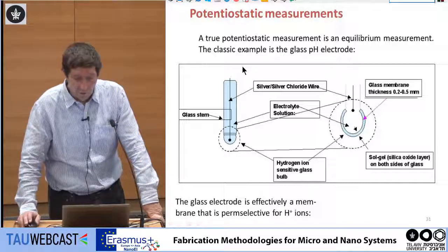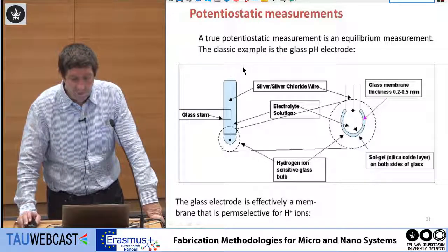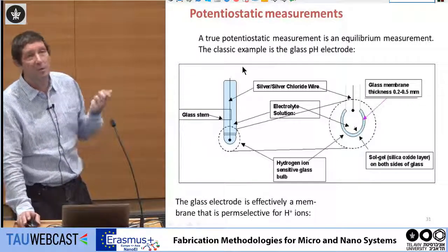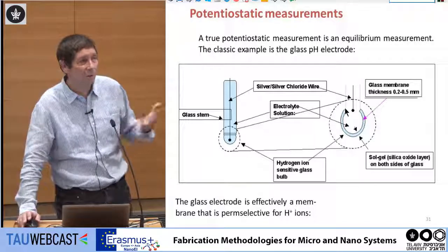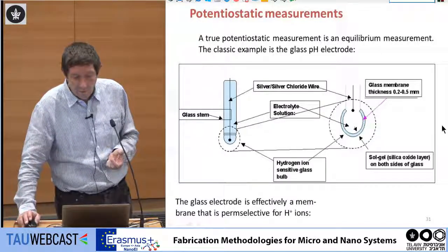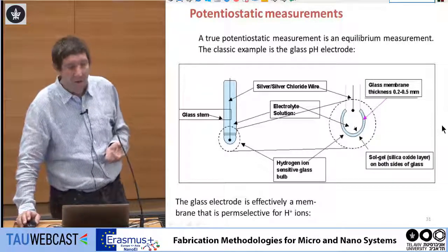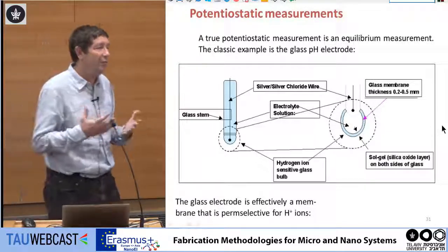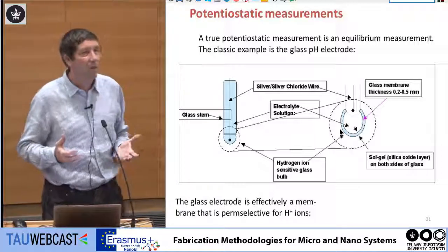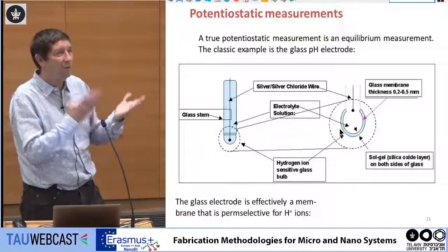So you take the electrode and deposit it. You can deposit by sputtering, by plating, using the tools that I told you before. But you wrap it with a glass membrane. One of the key factors in sensors is what we call selectivity. As I told you before, the electrode depends on the potential of the solution.